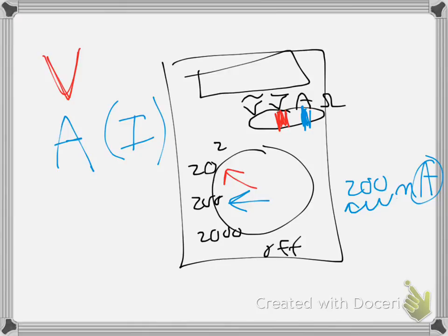If you want to use a multimeter to find resistance, which is your omega, just turn it to the omega. You can do ohms on all of these, but we will be doing the continuity test more than anything else in here. And that just lets me know if my current has a break or not.